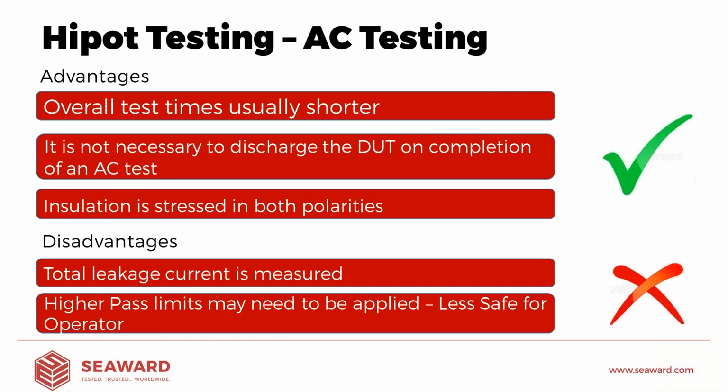So just to briefly summarize that conversation, AC testing, from an advantage point of view, overall test times are usually much shorter because we haven't got to consider ramping and discharging. It's also not necessary to do the discharging. And the insulation is stressed in both polarities.